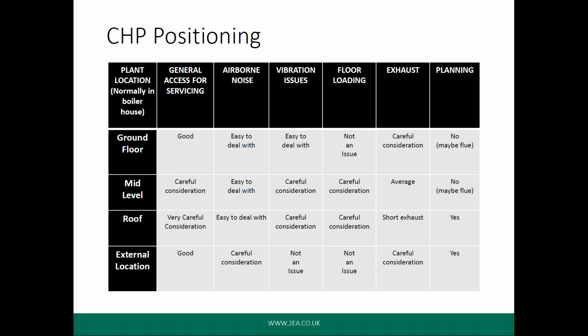The combined heat and power unit, when it's being serviced, just like your car, needs its oil changing at regular intervals, and it helps to reduce service costs if a pair of local oil tanks can be provided, one for the waste oil and one for the clean oil. I would go as far as to say that servicing of the larger units, greater than 300 kilowatt electric, is not really practical without the provision of such tanks. Your chosen supplier should be able to advise on the optimum tank size for your chosen combined heat and power unit. These tanks don't necessarily need to be directly adjacent to the combined heat and power unit, as they also have to have a fill point located near vehicle access for the tankers to fill and empty them.